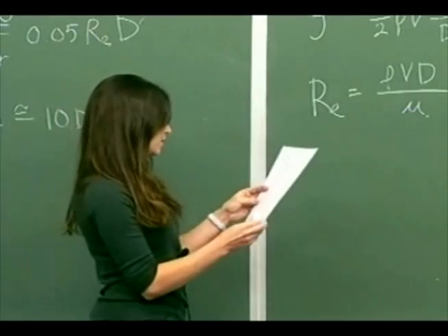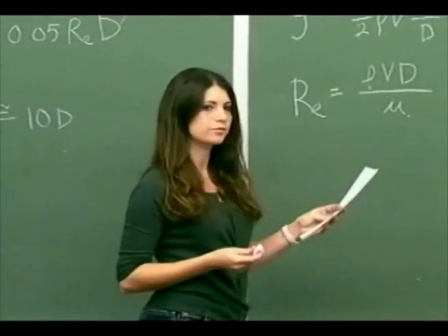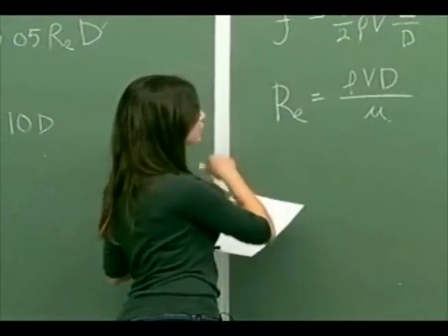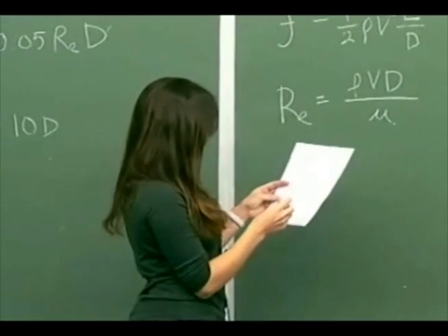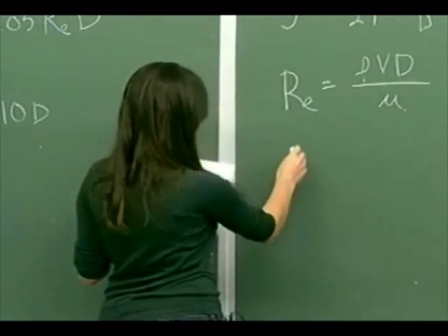What you're going to be comparing also is you want to look at the theoretical friction factor in addition to what you've measured. And the theoretical friction factor can be found from the Colebrook equation.